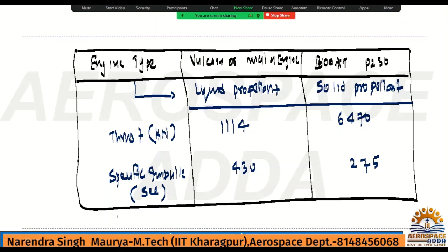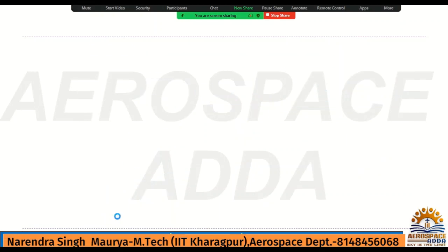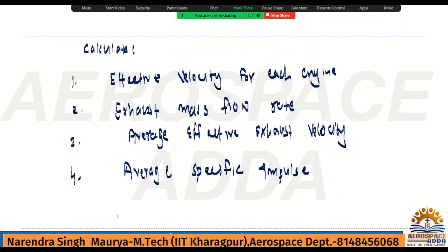Most of the time in the problem itself they will mention it, like here: one main engine and 2 boosters are used during the lift off condition. Simple, it means it is parallel multistaging. That's the reason I told you, just wait and see, you will understand once we solve both numericals, series and parallel. It will be very clear in your mind: okay, this is a series multistaging rocket system and this is a parallel multistaging rocket system. Hope this is clear, right?